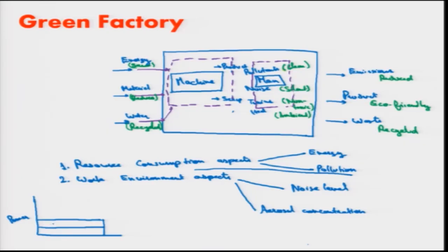It can be divided into two components here. One, I can say the computer or fans and coolant pump, etc. Next is spindle, okay, then tool change, etc. That is where the time is consumed. So this is almost constant. The variable energy that is there, that is the machining energy. Okay, this is variable energy. So this part is variable and this part is constant.